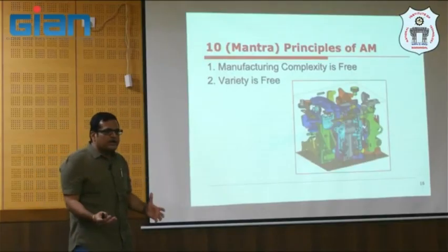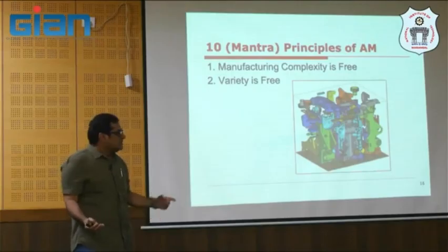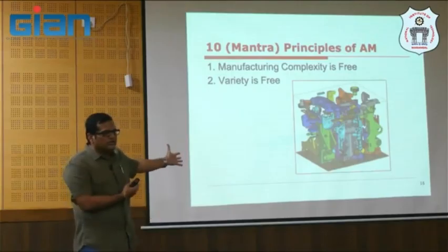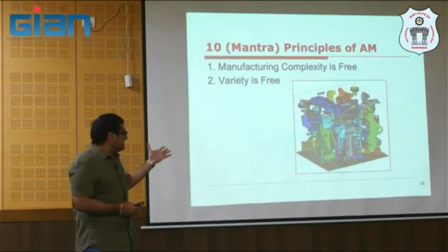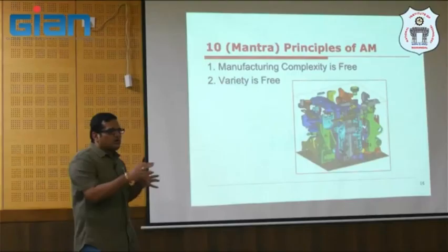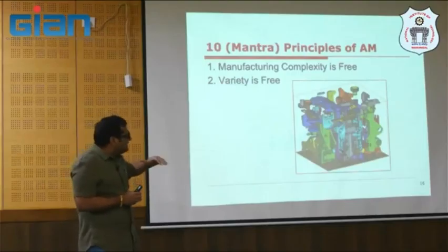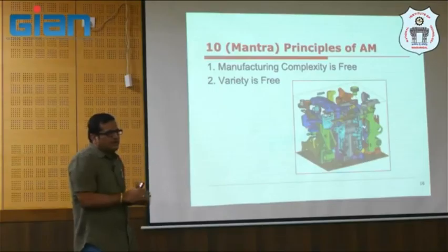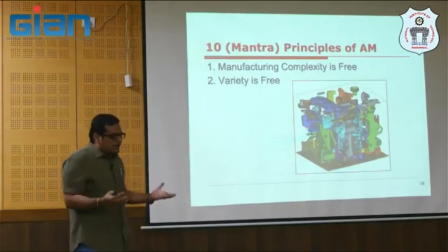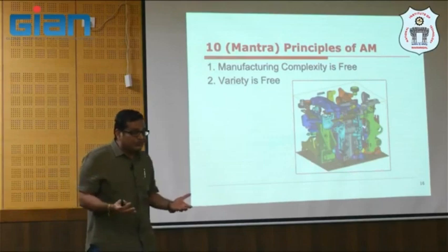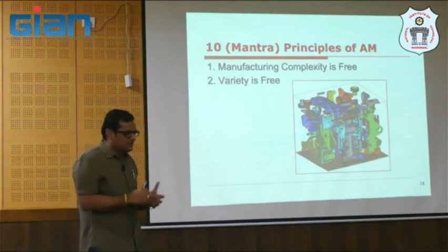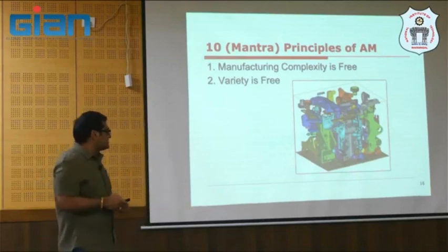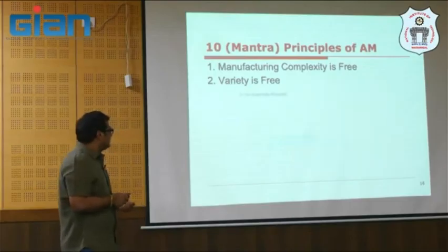If you try to adopt any conventional method, we need to write at least that many programs if it is CNC, right? But here in additive, it won't care what kind of geometry that is. In a single setup, you can make all these layer by layer. It won't care what kind of geometry you are printing. That is not the case in any traditional manufacturing system, right? So your variety is free.